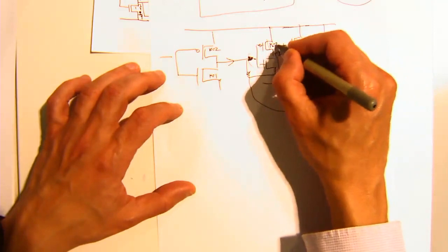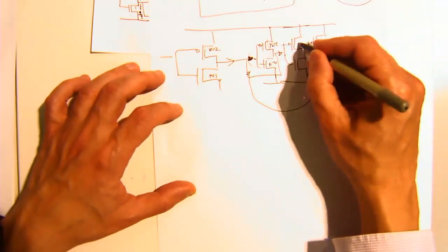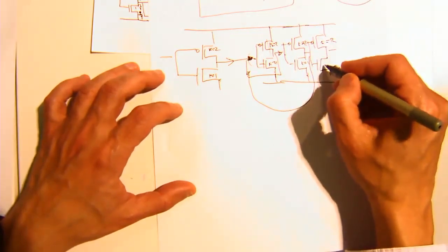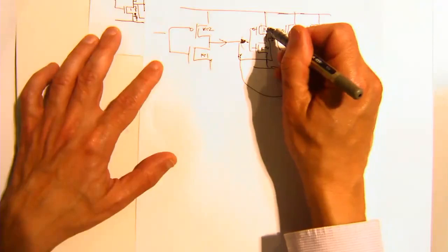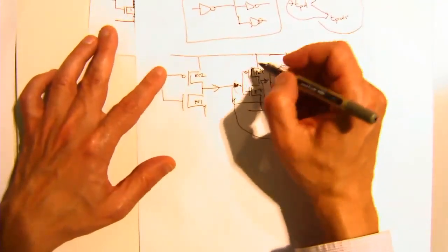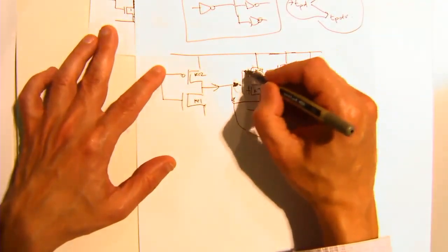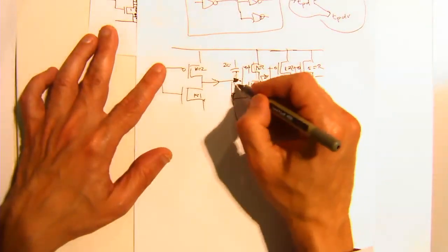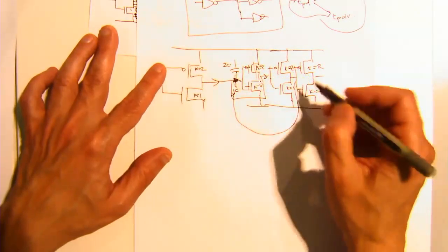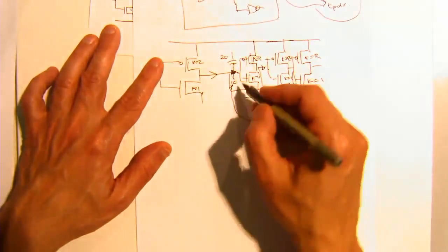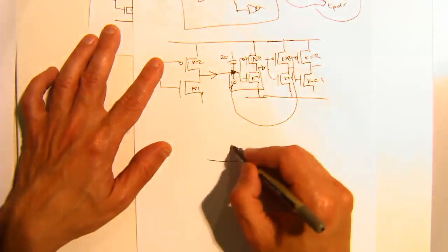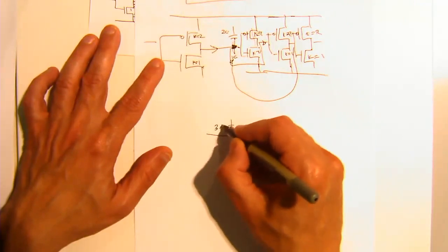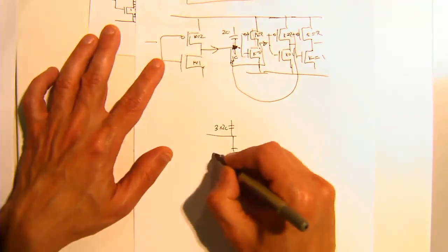If this is K equals 2 and this is K equals 1, what do we say here? Okay. So there's a 2C up this way and down this way. C, 1C, perfect. But there's 3 of them, right? So what we would be doing is, yeah, you can multiply. Yeah, exactly, because they're all in parallel, right? So you can go 3 times 2C plus 3 times 1C.